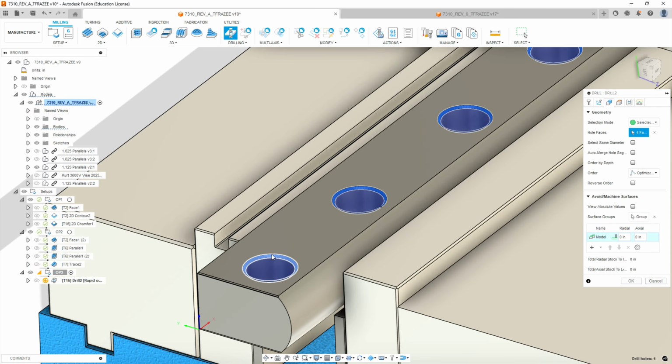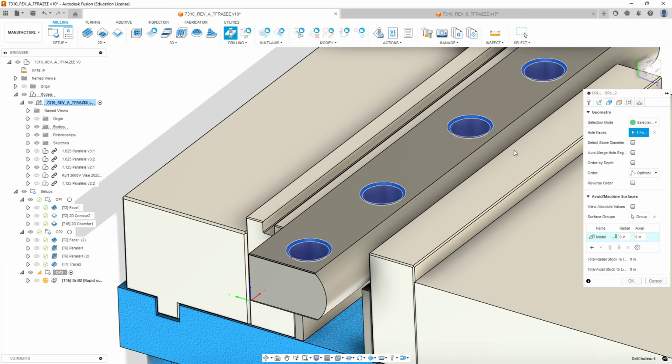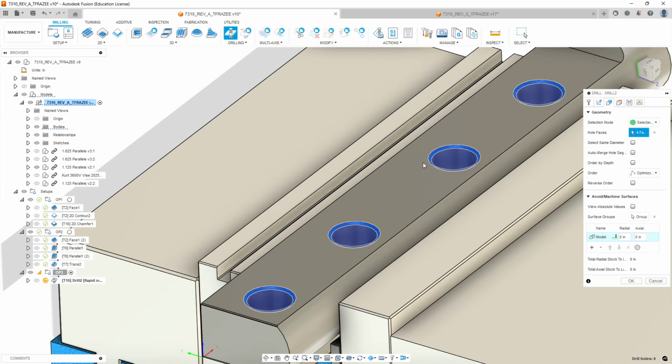It won't cut this actual chamfer, but it will spot drill down to a certain depth, based on the centers of it, because this is only a 3/8 diameter spot drill. A spot drill is actually a little cone cut that's slightly bigger than the web of the drill bit. The web is the very center of the tip where the two flutes come together, and it's ground sharp there. So we don't have to go very deep.